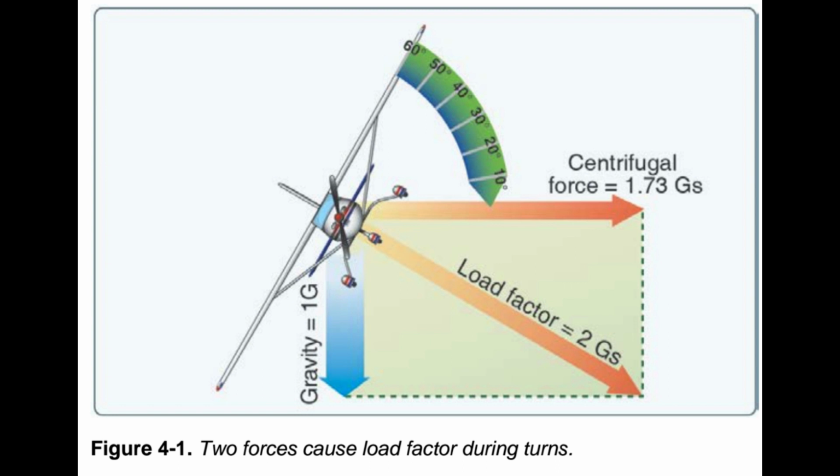The designers determine how far the center of pressure, CP, will travel. It is important to understand that an aircraft's weight is concentrated at the CG and the aerodynamic forces of lift occur at the CP. When the CG is forward of the CP, there is a natural tendency for the aircraft to want to pitch nose down. If the CP is forward of the CG, a nose-up pitching moment is created. Therefore, designers fix the aft limit of the CG forward of the CP for the corresponding flight speed in order to retain flight equilibrium. Weight has a definite relationship to lift.